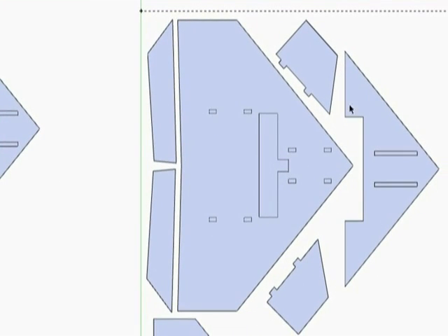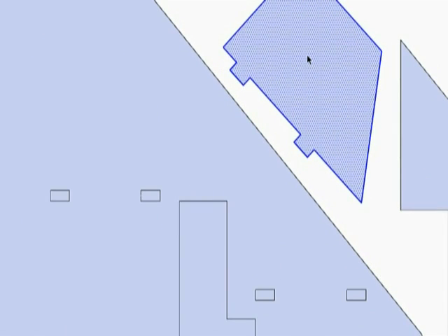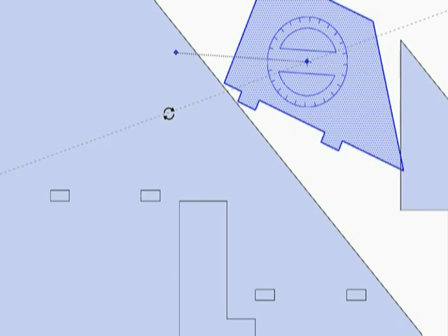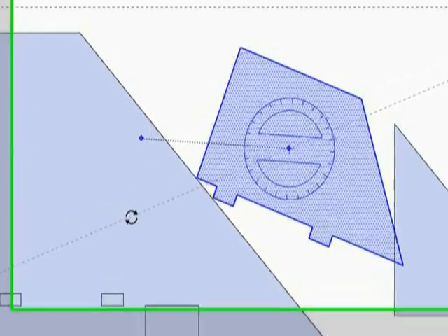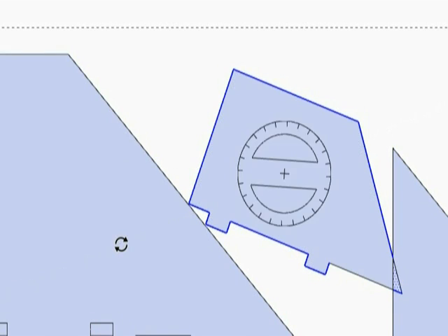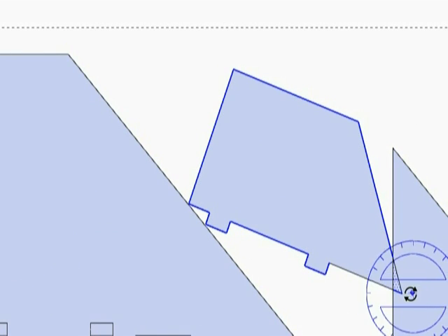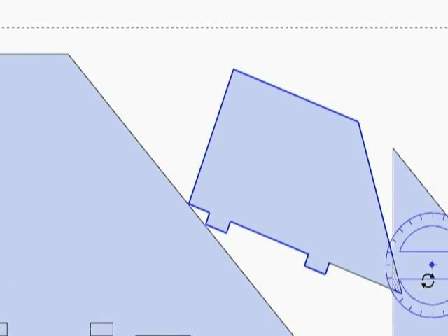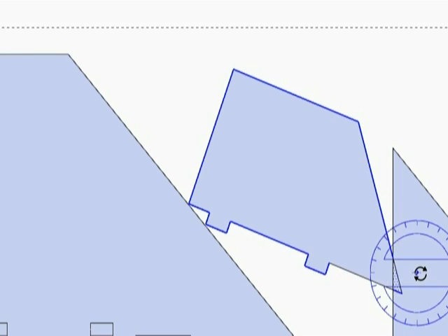Now also, these parts were not all turned and rotated like you see here. I did that to maximize the foam use. And one thing I wanted to share with you, as you're working with parts, I've got it selected. If I hit my rotate tool, then I can click on this part and work it around. Well, if I were to let that part touch and then I release it, now this part has become part of this. These two parts have become one.